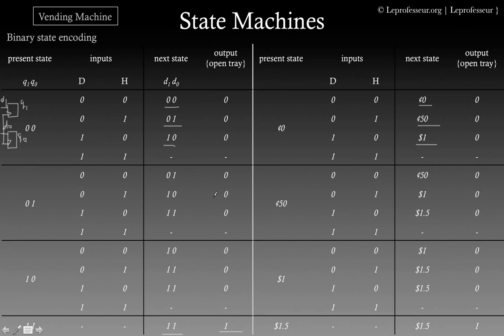Now, is that the only kind of state encoding, or is it preferred? Maybe not, because sometimes your two inputs are changing. If your machine is moving, and if it is binary encoded, it has to change 2 bits if it is going from 01 to 10. Since two inputs are changing at the same time, there might be a risk for glitches.